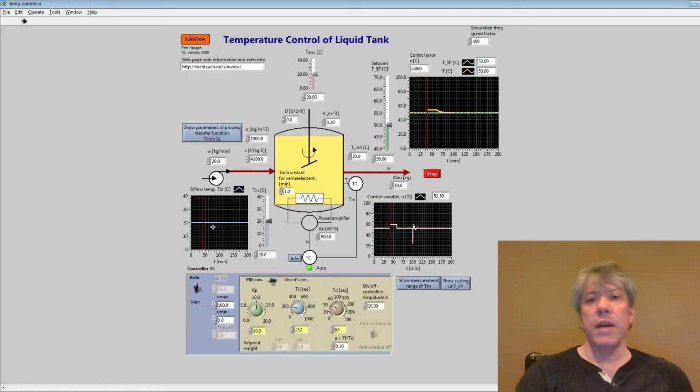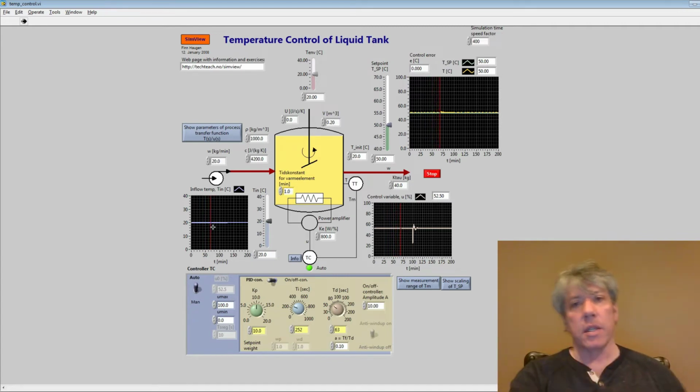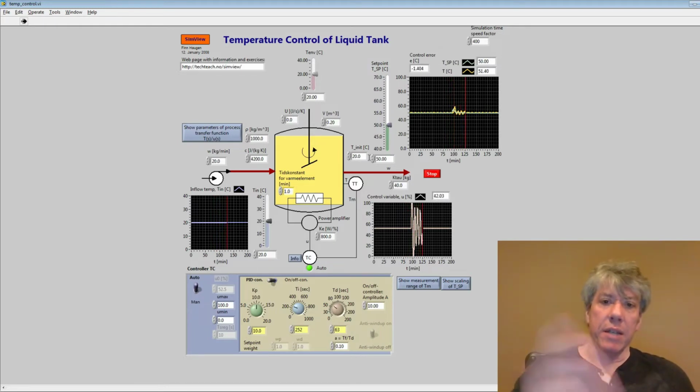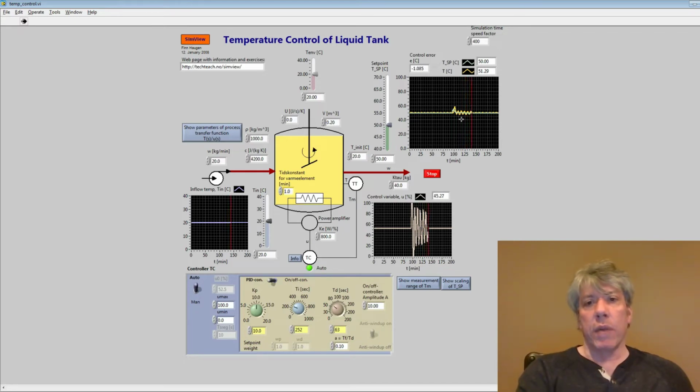And then I have to somehow introduce a disturbance so the system starts to ring. It starts to oscillate. I can do that by bumping the set point, which I'll probably do. So notice I take it up to some value and then take it back down. Not too crazy. But what I really want to get is nice, even oscillation around the set point. You can see that it's oscillating well.